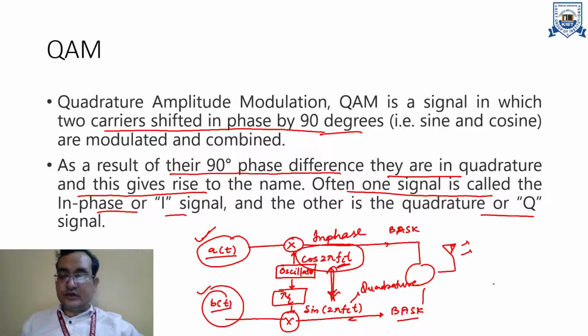If you draw the spectrum, you can see that at fc there is a single frequency component, because if you are drawing the spectrum with the help of CTFT, then you will only see the magnitude. Considering the magnitude, you will only see the single frequency component. But if you apply the phase spectrum, then you can clearly see the differences, right?